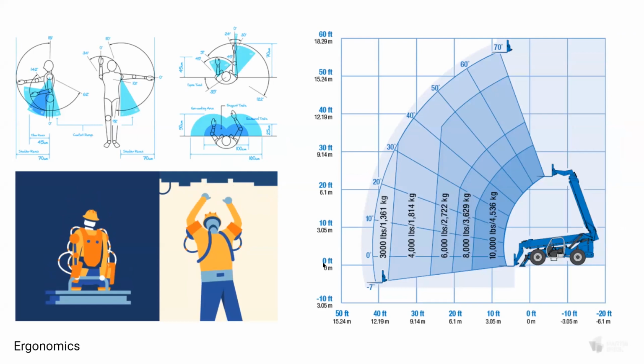Installation is another area of industry overlap, this time with manufacturing more broadly. Our study assessing if the final install position for each panel can be reached with our equipment directly parallels the ergonomic studies for an assembly line, which ensures that workers can safely perform any given task. For us, our forklift weighs 50,000 pounds, and on a complex site with other trades working at the same time, it's not like you can just drive it anywhere. We have to make sure that given where the forklift has to be positioned, the panels that we need are all within reach based on each panel and its substructure's weight.